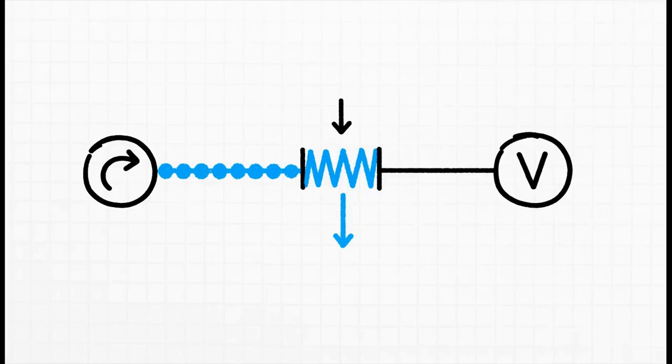Let's take a look at circuit A. Here, we're forcing a known current through our device, the DUT, or device under test, and we measure the voltage across it. Seems logical, right? But for a high-resistance DUT, this is a total disaster. Why? Because your voltmeter isn't perfect. It has its own internal resistance. So by connecting it like this, you've accidentally created a second path for the current flow, basically stealing some of it from your DUT. Your voltage reading is going to be way off.